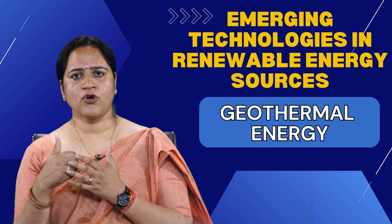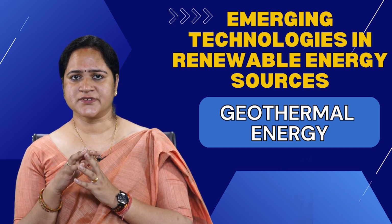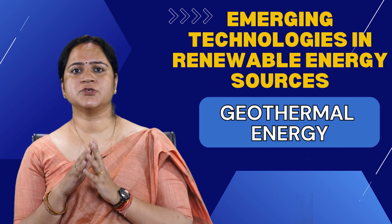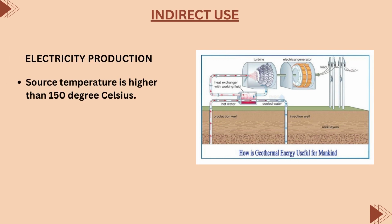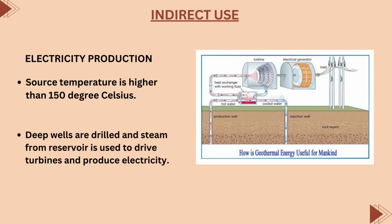Now if we talk about indirect use, the end energy form that we desire is electricity. So we utilize this geothermal energy for electricity production as well. Here the source temperature will be higher than 150 degrees centigrade, and to extract this thermal energy we have to dig deep wells. Deep wells are drilled and steam from the reservoir is used to drive turbines, and from the rotary motion of these turbines electricity is produced.